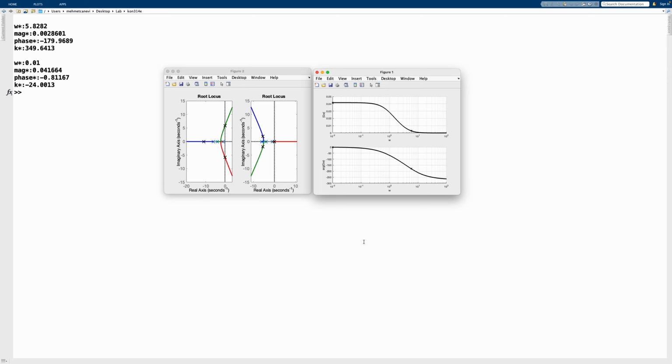And if we would apply a step type input, we still would get a sine wave. So this would correspond to 100% overshoot, because it keeps increasing and will get out of control, so it's not going to be stable. We know for a fact that if we are at the j omega axis, even if we apply a step type input, the output will be a sine wave, and that will correspond to 100% overshoot.